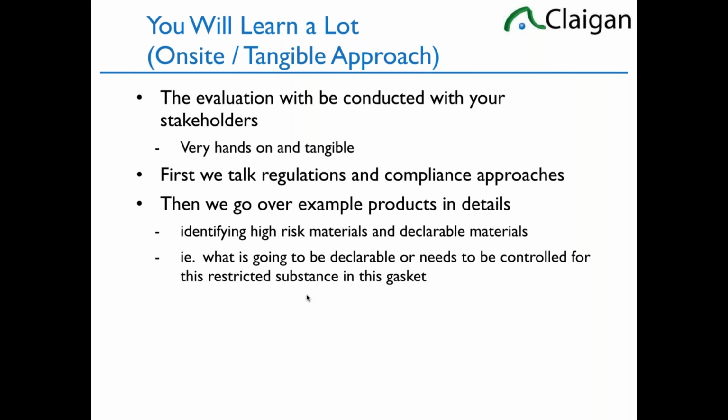But one thing we really want to do is move compliance forward, up front in the process. Like what a lot of companies do for EMC, or electromagnetic compatibility, testing, where you take it for granted: when they're designing it, the designer puts EMI gaskets in there because they know about the EMC side. You could do the same sort of thing for restricted materials. Often with the power cord, if you did design work so it doesn't have phthalates, it has terephthalates or something else, you could have done that up front and it would save you so much trouble. If you pick this gasket, if you pick this one material over that material, you wouldn't have all these problems afterwards. So the knowledge takes a step. Nobody's going to learn everything in one day or remember everything. Move it farther up front.